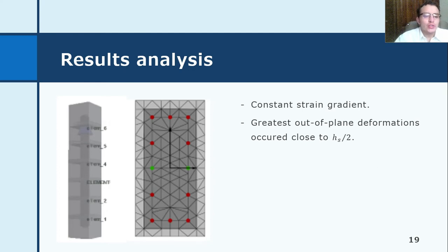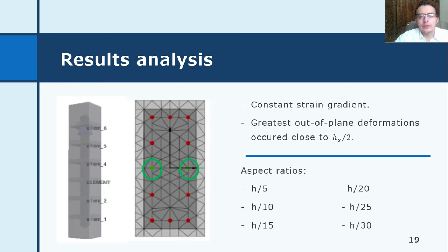As usual, some data also had to be removed, so boundary elements with an aspect ratio of h/30 were discarded due to convergence problems associated with the insufficient cross-section to carry the load cycles before experiencing out-of-plane buckling instability. Other discarded specimens were those with an h/5 aspect ratio and some with h/10, since they exhibited concrete crushing because of robust cross-sections. In other words, the extreme cases pose a problem because they are either too strong or too slender.